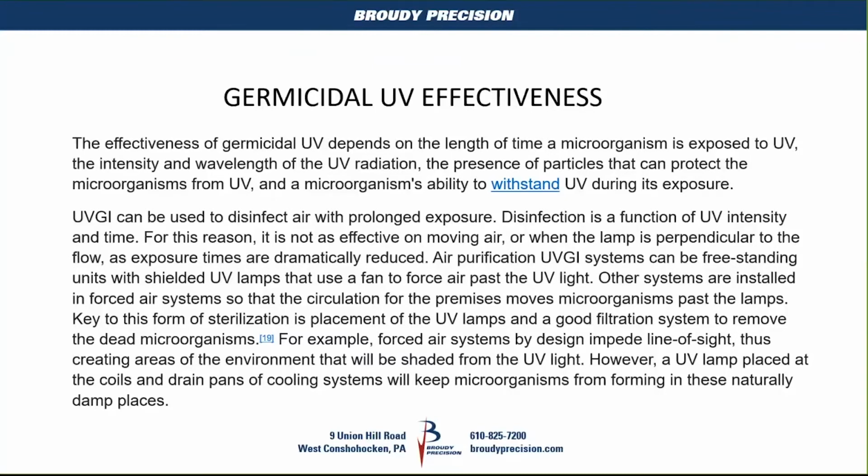A lot of times, the best practice is you'll see these UV lamps installed on the leaving side of a chilled water coil or a drip pan, and then you'll see another one downstream a little bit further. We don't always have that kind of space in air handlers to be putting on all kinds of UV light racks, so that may or may not be an option. So what you do there is you have to have more intense UV light for the area in which you're installing them.